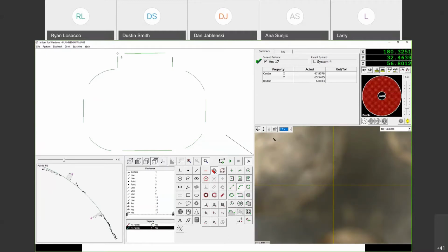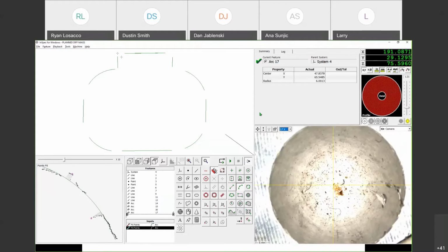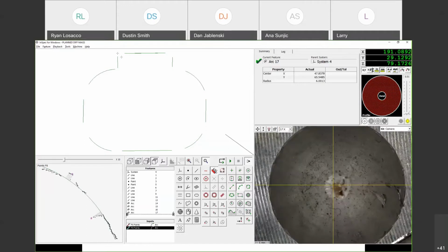Cool. So a really reflective part here. I'm going to adjust my lighting. Sidebar lighting tip: a lot of the time I'll forget to check the axial light to see how axial looks. If I want to get this diameter here, when I was talking about a lot of the noise we have going on, this is what I mean: I have a lot of gray value inside the cone. And on top, that machine surface, we've got a lot of noise going on, a lot of gray value.